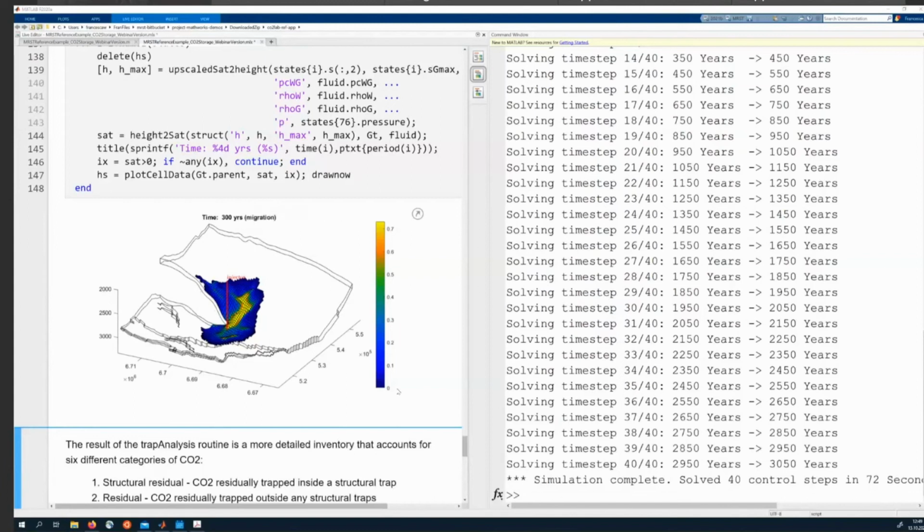So maybe a little bit more context with regards to the efficiency. I would be interested to understand the buildup in pressure in the reservoir while you're doing that, so the capacity for the reservoir to actually take the injection, because you might get to a point where you're above fracture gradients, and then you're fracking the well instead of injecting the gas. And yeah, that might not be something that you want.